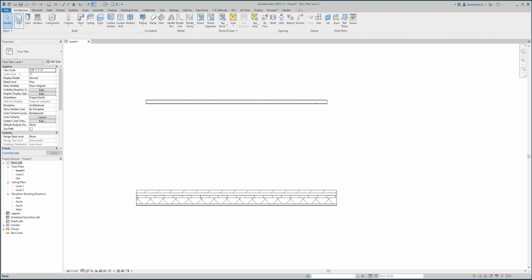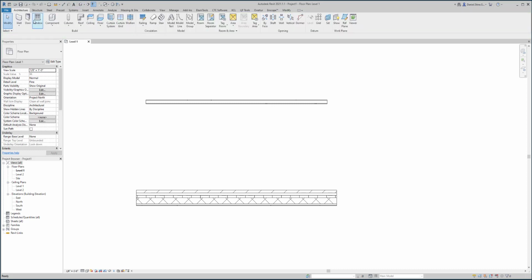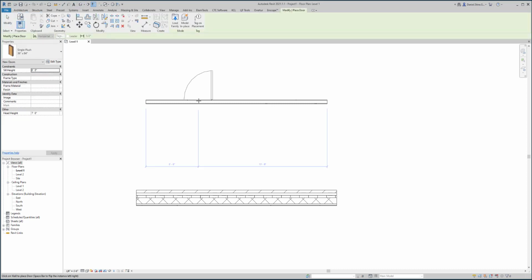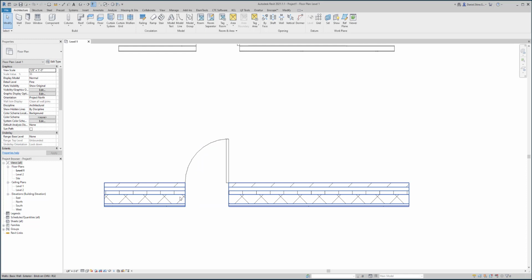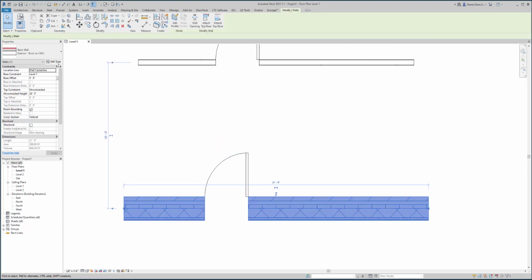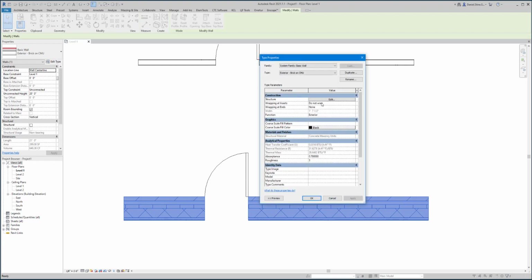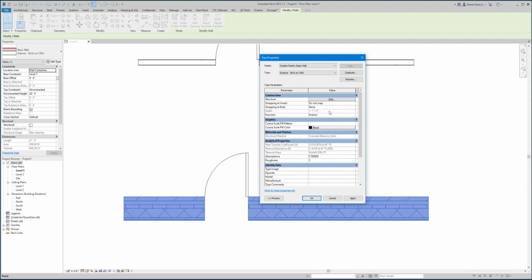What I mean by that is we will start by adding a door to two different wall types. And by default, the materials in the walls do not wrap. If we select the wall itself, not the door, we can control wrapping at inserts, and that's also tied, as we'll see in a moment, to what's checked here as wraps.